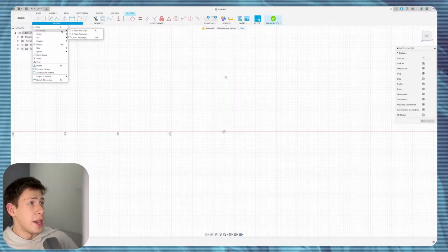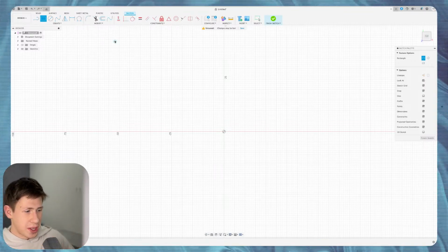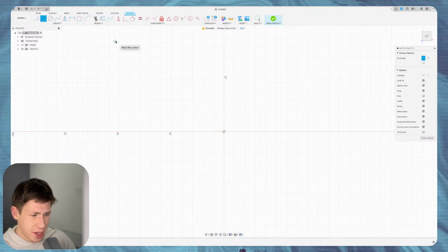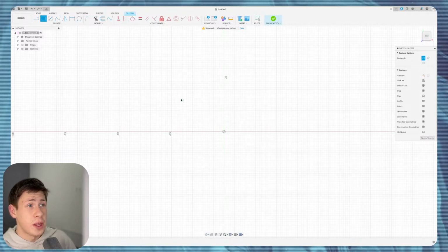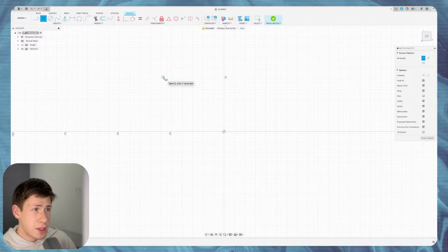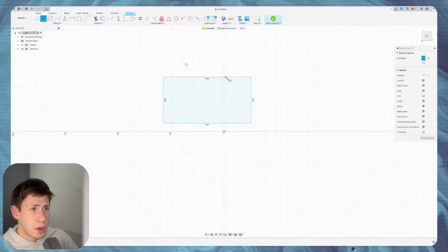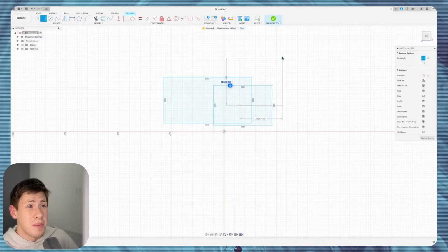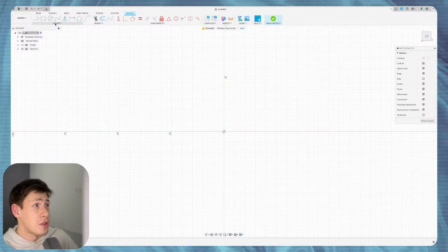Next in our list is rectangle. I showed you actually all of it while exploring the circles, but first rectangle is 2-point rectangle. You select first dot, then second, and here it is. So this is the basic rectangle that you will use in daily work, and a lot of different work is based on this tool, but we also have more convenient options.